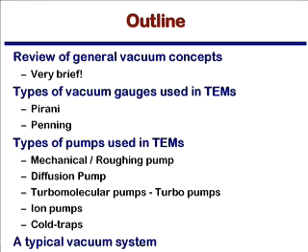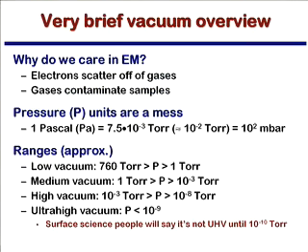One of the problems that can happen is if your samples have excess hydrocarbons on them from things like your finger grease when you were making the sample, glues when you were making the sample, those things can become problematic. They'll tend to agglomerate where the beam is, and so it's good to have a good vacuum for lots of reasons, all right? So really those are the two reasons that we care. It's to make sure that we have a reasonable vacuum so we don't have too much scattering in advance of and after the interaction with the sample, and also we worry about the contamination.